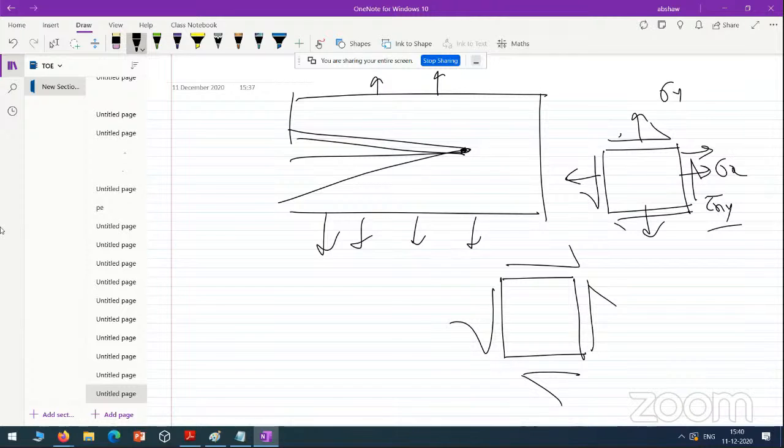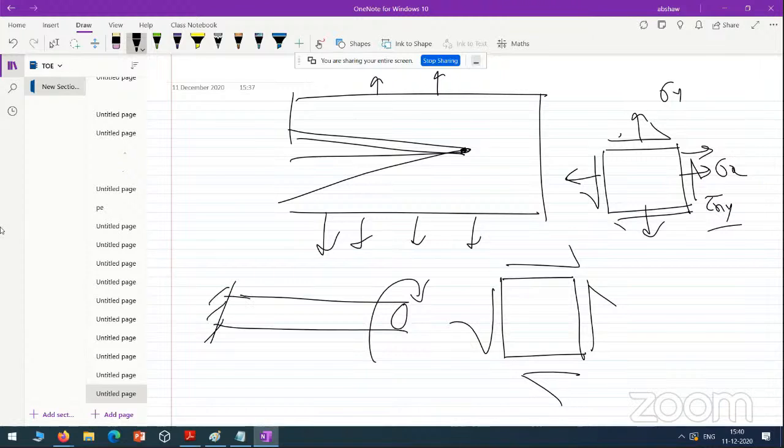Yes. Suppose you take a circular shaft with one fixed end and apply some torque. Then at any point, the state of stress will be pure shear. Then there is another question attached to this: is there any example where there is no shear stress, only a state of biaxial stress? Yes, again, there is an example.